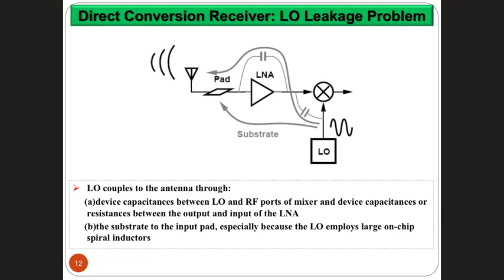So basically this signal, this local carrier coming from here, will end up being what at the output here? Amplified. DC offset, exactly. That's the second problem that we'll discuss. So the first problem is the leakage that comes from here creates a signal that can affect other receivers. The other problem is the self-effect here is going to be mostly introduced as a DC offset, because you have a cosine with fixed amplitude, which is being demodulated by itself. Right? So you end up at the output here, this leakage ends up being a DC offset.